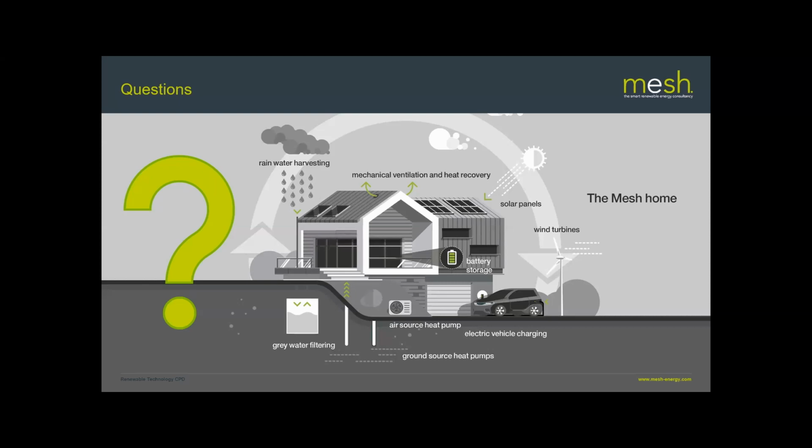So the question then is, do you want to have simultaneous heating and cooling? In most cases, you won't want to, but if you've got a particularly awkward property where, for example, you had one room that was very prone to overheating, even in sort of March time, it was a particularly bad room for solar gain, then you might want to do simultaneous heating and cooling. If you want that, then you have to have 2 buffer vessels, and then the heat pump will be allowed to flip between heating and cooling.